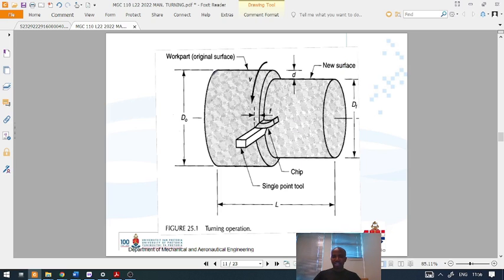We have a component to be held at the side by the spindle, the jaw, initial diameter, and then this is the final diameter that you are looking at, df. That's the depth of the cut. You can achieve this by multiple cuts and multiple passes. A cut is going to go down, a pass is going to be going sideways. So this is a pass.